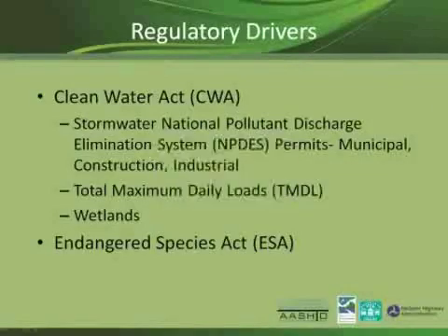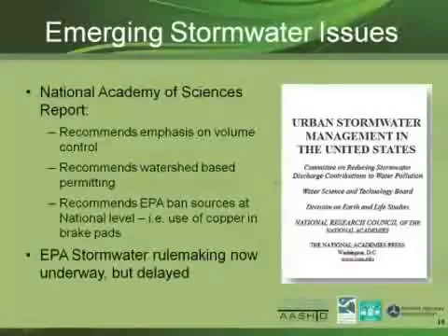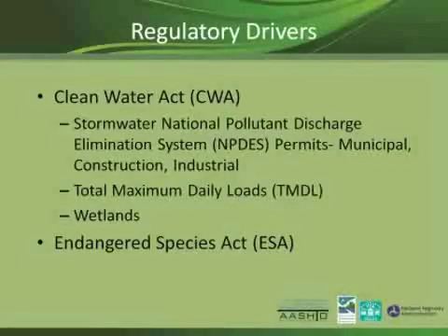There we go. Some of the regulatory drivers are the Clean Water Act. Some of the drivers that require DOTs to implement post-construction BMPs is primarily due to compliance with the Clean Water Act, National Pollutant Discharge Elimination System, or our NPDES permits. Post-construction BMPs are incorporated as part of our projects and as part of our new construction, project reconstruction, and through our retrofit projects. We also are required to comply with total maximum daily loads, which are mandates for fixing impairment of a water body. TMDLs require us to retrofit post-construction BMPs to meet waste load allocations assigned to each Department of Transportation.